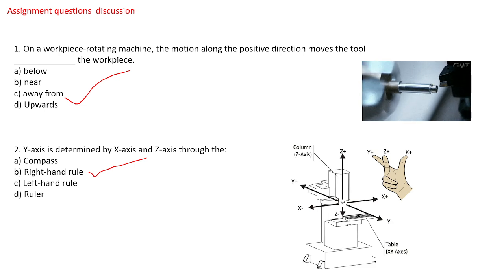Another thing is that, depending on the kilowatt rating of the laser, it will have a heat affected zone. That is the reason I told you that due to the heat affected zone, subsurface damage happens because of flame ignition; it actually catches fire in some materials. So we need to do some post processing after that.